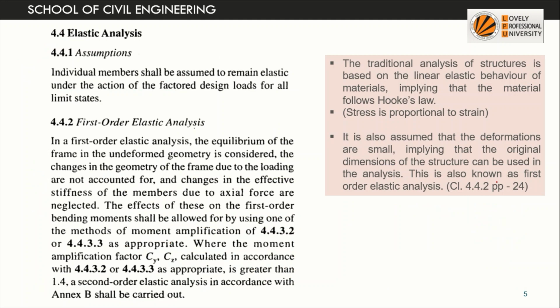Now you can refer to page number 24. You will find some data given on the elastic analysis, and what it essentially means is that it obeys Hooke's law, meaning stress is directly proportional to strain. The other thing is we are assuming that the deformation is very small, so we keep the original dimensions of the structure for the analysis, and this is known as first order elastic analysis. This is the first order elastic analysis we do in the case of elastic analysis.